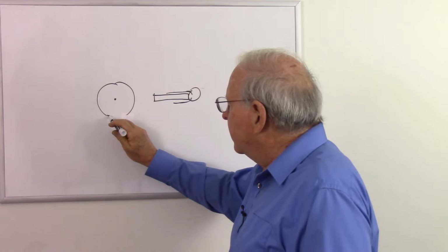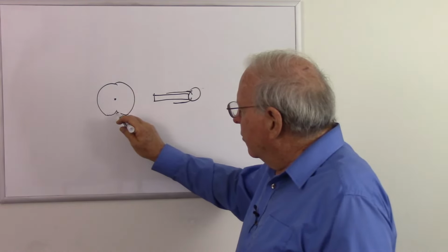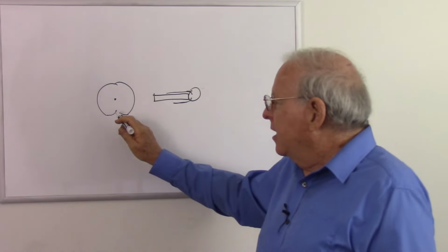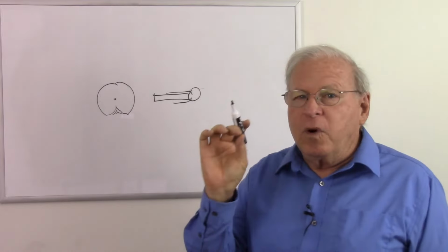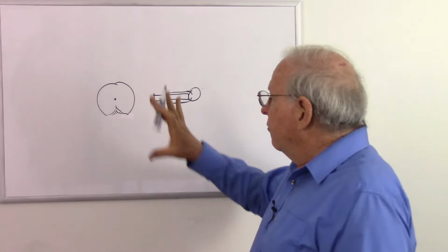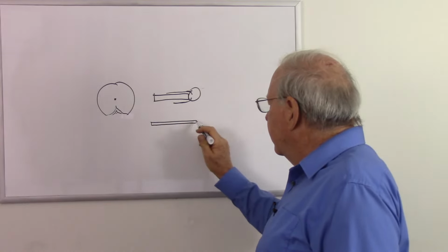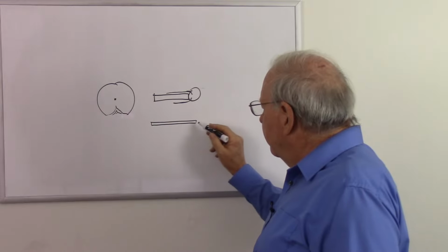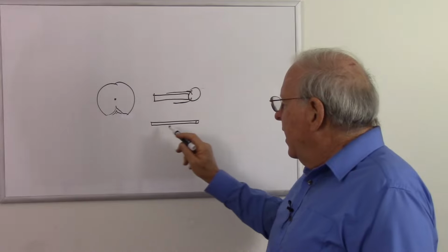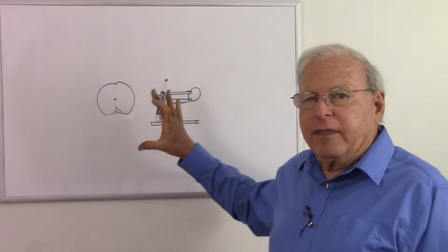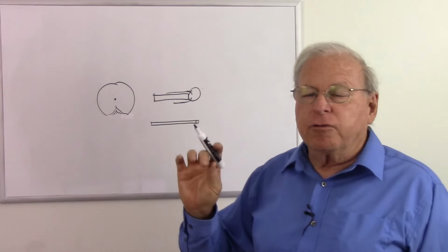Let's just draw a little bump in there. Maybe it might even be worse. At higher and higher frequencies, it will be worse. So at high frequencies, you might end up with something that looks more like a cardioid than omnidirectional. So if they really need the omnidirectional characteristics of the microphone, they will make the microphone barrel very thin. I'm drawing about 5 or 6 millimeters, and that would be the ideal with no dust screen on it, just to show the microphone. This will not affect frequencies in the audio range. So as long as you're below 20 kilohertz, a microphone of this diameter will be truly omnidirectional.